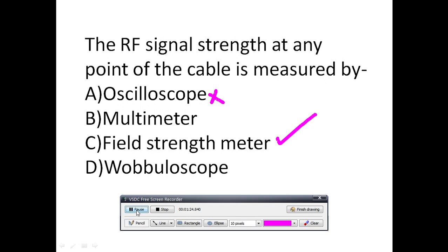In this video, we want to explain clearly about the Johnson counter, which is asked multiple times in the RRB JE mains exam. Johnson counter, also known as creeping counter, is an example of a synchronous counter. What do you mean by synchronous counter? Synchronous counter means, suppose CP is a clock. Now that same clock has to be given to each and every flip-flop as shown here.